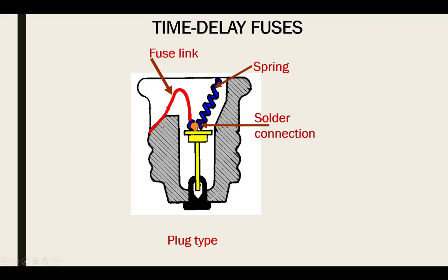It has to be hot for a long time, and this solder will melt, and the spring will pull the fuse link away. So a big surge is not going to be enough, but a continuous surge over a short period of time will be enough to melt this and cause this to open up.